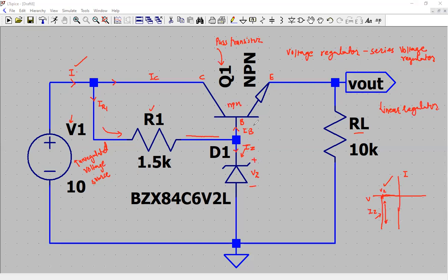So that's how now you see this IB is here, and the current that is coming out of the emitter is called the emitter current that subsequently flows into the load, that is the load current IL. When the load current IL flows through resistor RL, it develops a voltage drop across the load resistance, which is the output voltage essentially, or it is also called the load voltage.